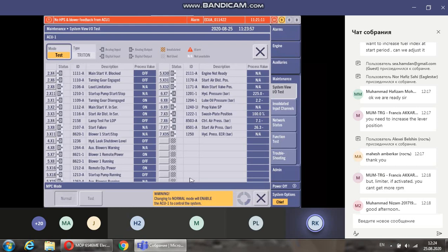Please keep in mind that if you are taking a controller, an MPC, into test mode, the engine should be stationary, as you are taking it offline, so it would reboot. You can see the values disappear. It's going to reboot into a different setup like we've just seen, so we're able to adjust output signals from the MPC. You can only test outputs, you cannot test an input, so you're only able to check what is coming out from the system.